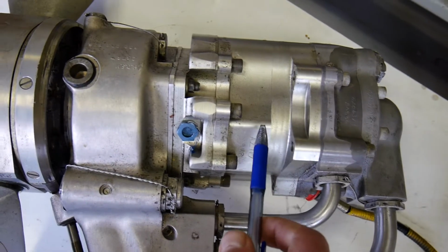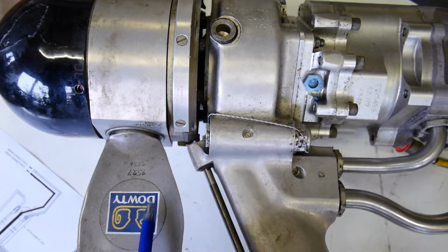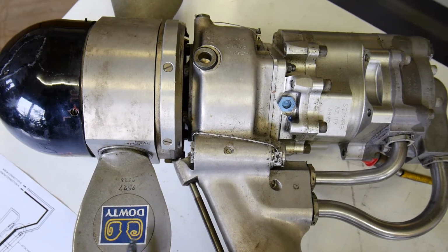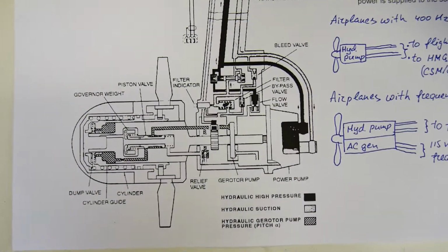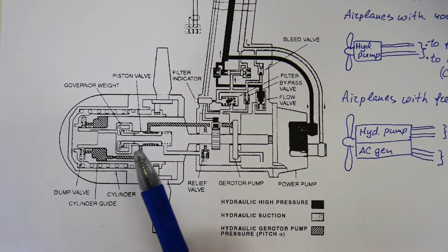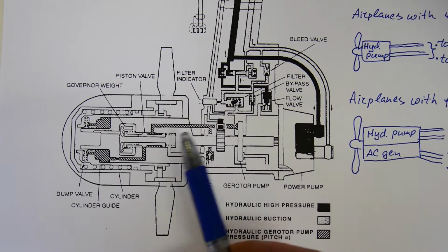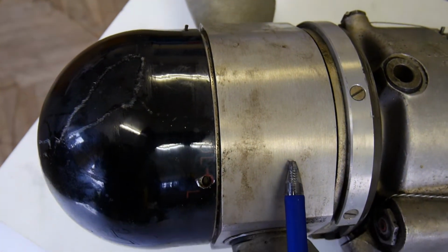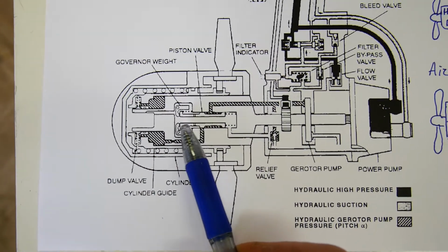Further, this is the speed governor of the fan, of the propeller. In this model, the speed governor controls by means of oil. This part has a centrifugal speed governor, which is here. This speed governor senses the speed of the propeller.